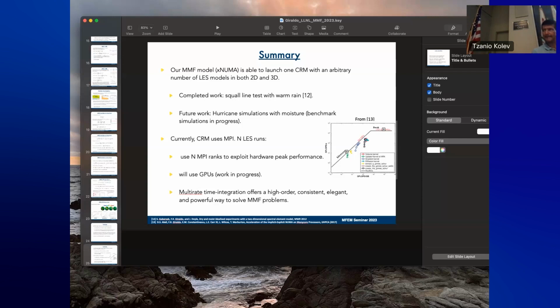Okay, for the phase terms that you have in your fluxes, how much of the element data do you need? Do you restrict first and then do things on the phases, or can you just use one or two layers of the model? Yeah. So the question is on the phase integrals for the flux terms. We're using Lobatto and exact integration, right? So we use only the terms along the point right on that edge, and that's it. So it's very cheap.